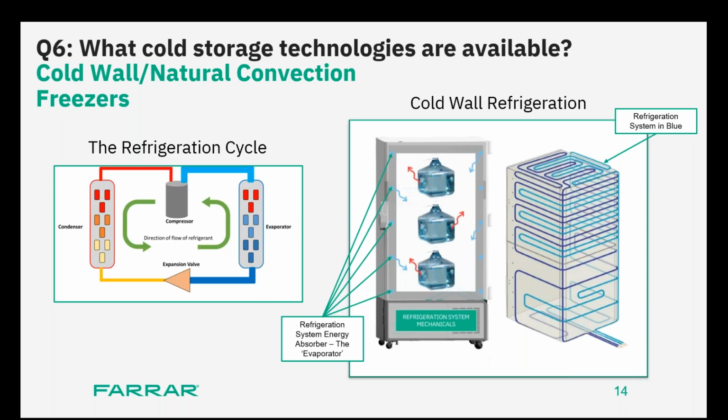So now imagine the operation. You have this carboy sitting here, right? And water is filled, so it's at 25. So what's going to happen is water will start to lose heat, and it will go from plus 25 all the way to minus 80. The coldest spot in this chamber is actually the surface of the wall, because that's where the evaporator is located, right? And the evaporator is the coldest spot. So that's how the heat transfer process gets into action here.